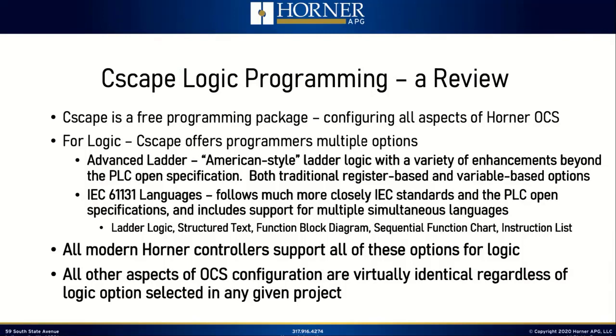And in doing so, we've added support for multiple simultaneous languages, like all manufacturers that support IEC 61131 do. So you have your choice between ladder logic, structured text, function block diagram, sequential function chart, and instruction list. You can use all of those languages, or some of those languages, on any particular project. And again, we've been supporting IEC for some time now. All modern Horner controllers support all of these options for logic.